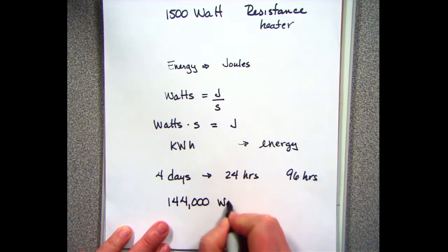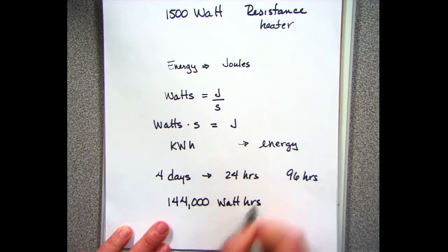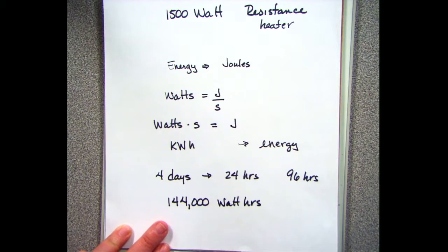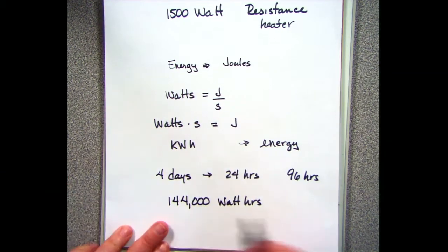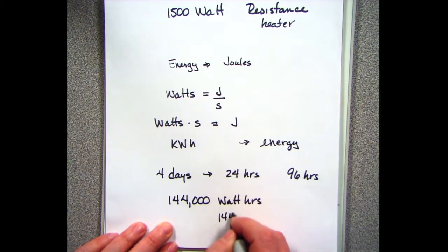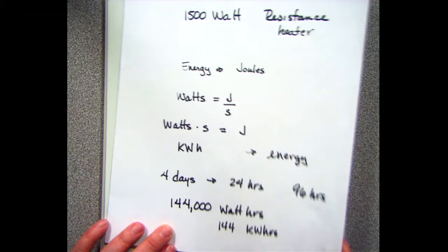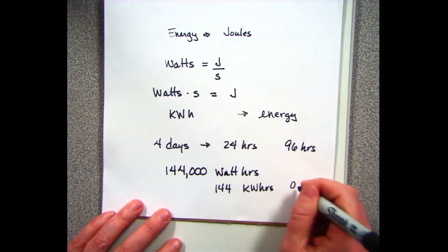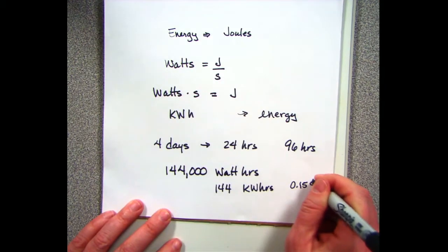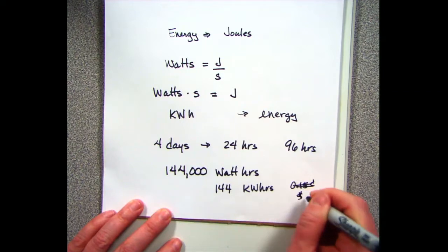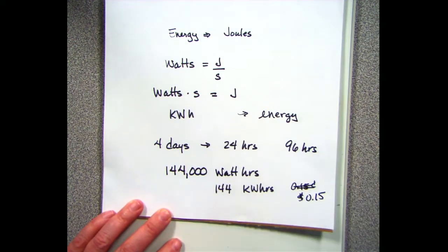And if I'm running at an average of 15 cents per kilowatt hour, it's cost me $21.60 to operate my little resistance heater to keep my bathroom warm so I don't freeze my pipes.